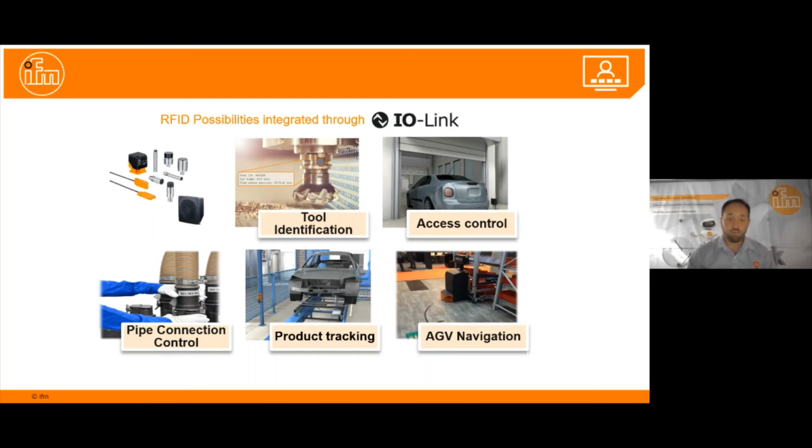So you would be transferring, in one hour, product from one tank to another, and the next thing you'll go into a cleaning phase where you actually introduce a pump that actually pumps caustic and hot water to actually rinse out the tanks and do what we call CIP of the tanks. So it's important that the hoses are connected correctly, and Ilink and RFID can facilitate that.